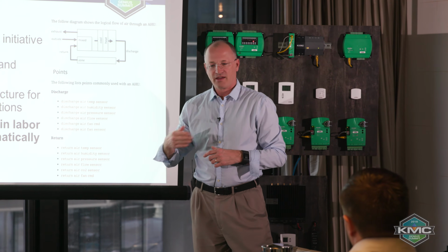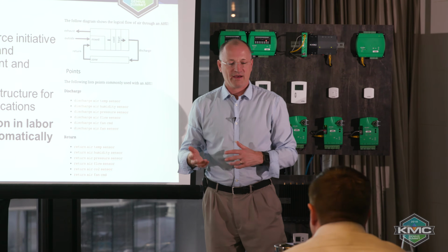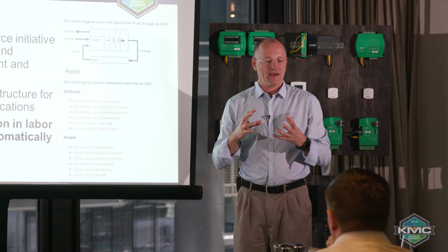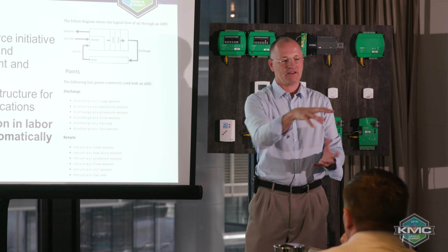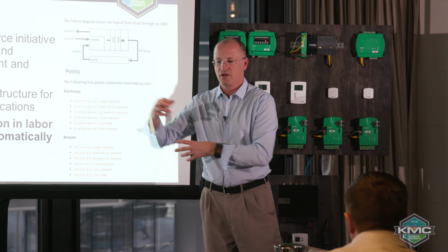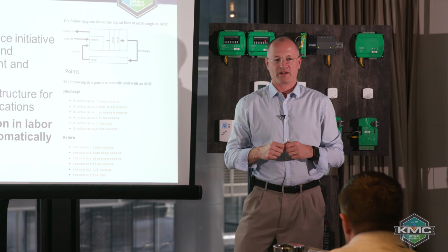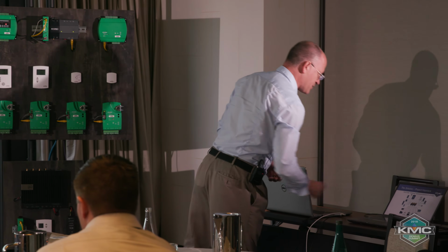So you can have tagging at the point level. You can have tagging also at a higher level, which would be at the equipment level. And by modeling VAV type 1 and air handler type 2, you can get huge payoffs of reusability and things that just automatically work. So let's get into the real world.